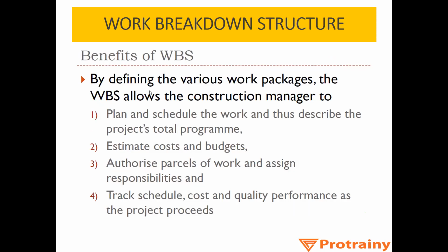By defining the various work packages, the WBS allows the construction manager to plan and schedule the work. That is why we divide it into packages, so that planning and control become easy. Different kinds of labor and machines are involved, and all the resources are different for different work packages. So it becomes comparatively less difficult to monitor when you divide it into different packages. This breakdown is known as work breakdown structure.